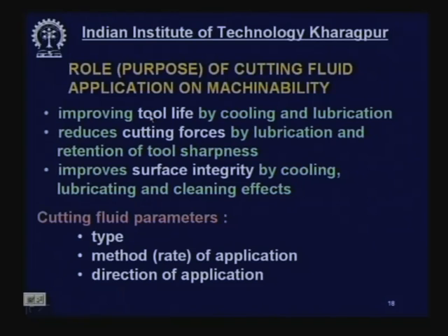Next, the cutting fluid, by lubricating and cooling, reduces cutting forces by lubrication and retention of tool sharpness. If the tool remains cool, then it will retain its sharpness by preventing plastic deformation and wear. It improves surface integrity by cooling and preventing built up edge formation, lubricating and cleaning the effects.